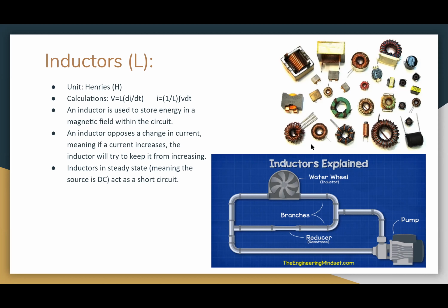Thanks, Tariq. So inductors, capacitors, and resistors essentially slow down current. Well, resistors slow the current down. Inductors really don't do that in a DC source. Instead, if you have a DC source connected to an inductor, the current's going to want to flow through the inductor, because the inductor is going to act like a wire rather than an inductor.